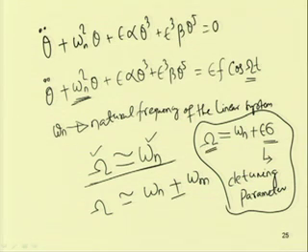Similarly, when omega is nearly equal to omega n plus omega m, one can have a combination type of resonance condition. So, in the case where omega is nearly equal to omega n, one can have the primary resonance condition, and in this case one can have the combination resonance condition. In the combination resonance condition also one can study omega nearly equal to, let me take only the first two modes, omega 1 plus omega 2 plus epsilon sigma.